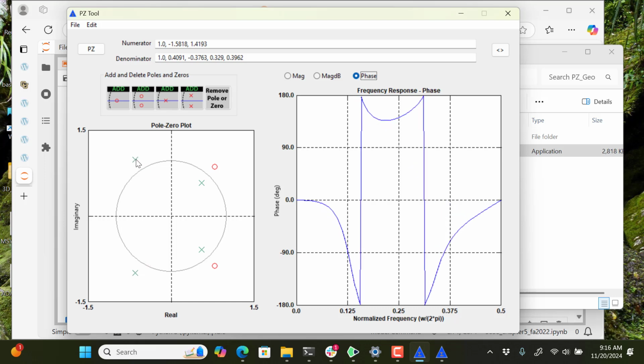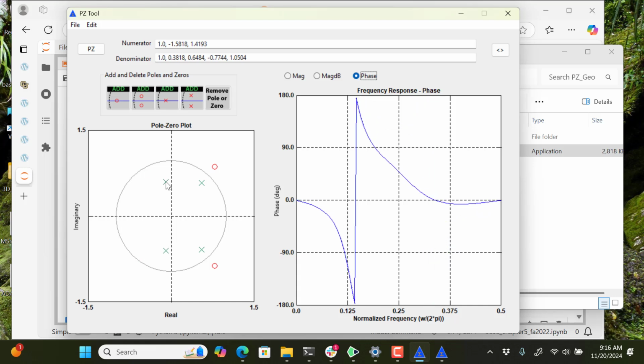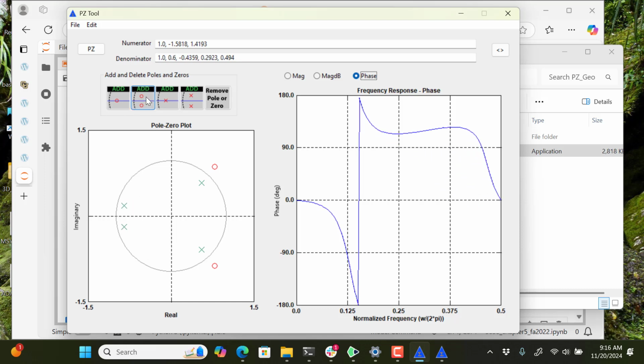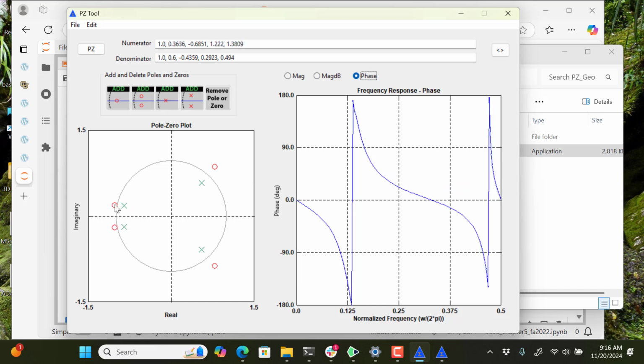And in my software, notice, because I'm only doing magnitude response, I can put poles outside the unit circle because I can think of this as being anti-causal. It's mathematically implemented, but I know I'm not going to build a real-time causal system. I could put another one of these over here and try to drive for the same thing.